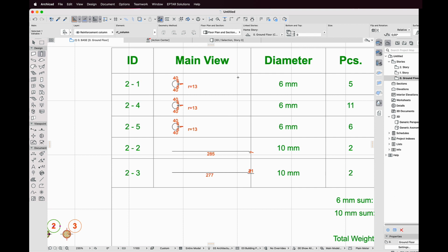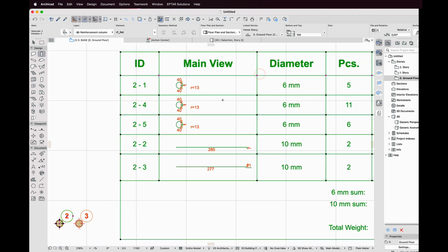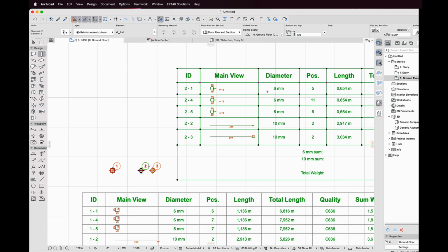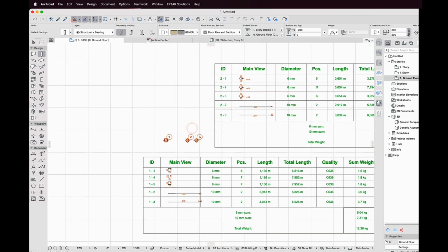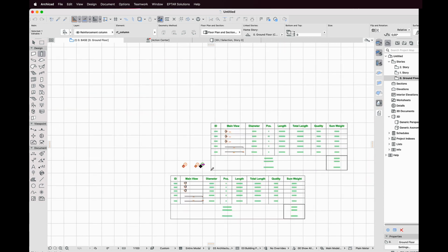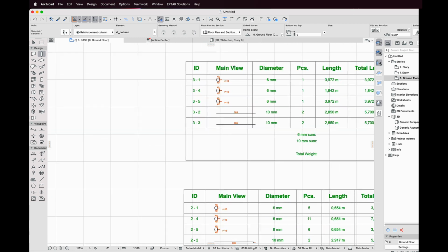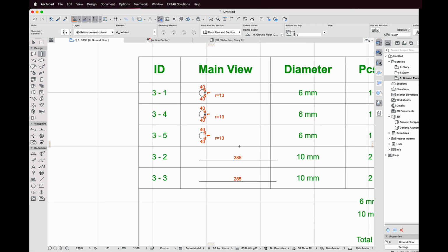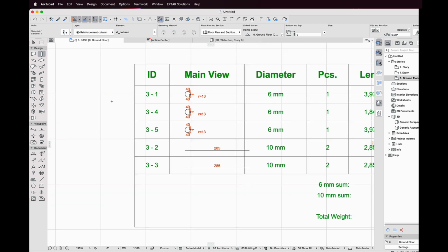I modified the list separator border a bit because there is not enough room for the rebars view. And lastly, I select the reinforcements of column number 3 and click on the Cutting List tool again, then place the list next to the element. Here the spiral stirrup is listed as one piece in each group and the full length is indicated.